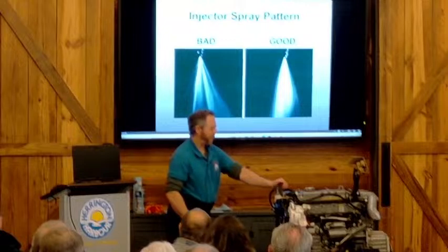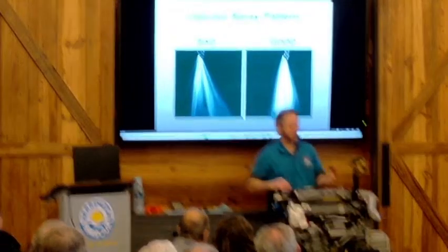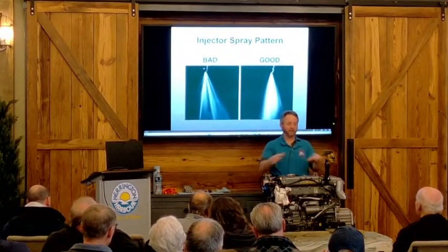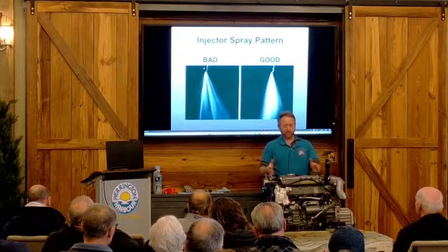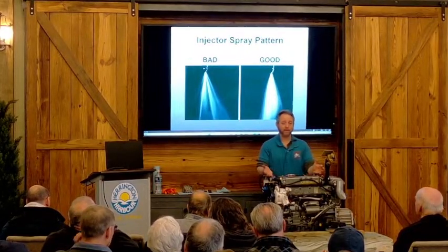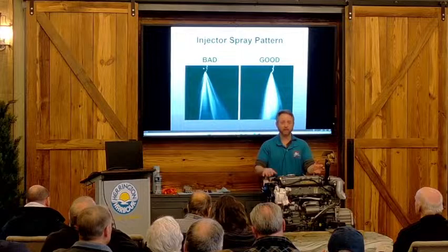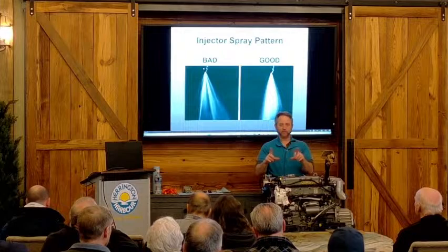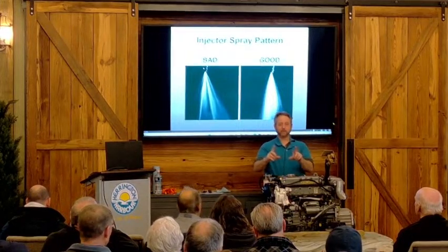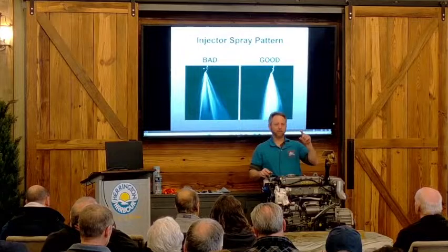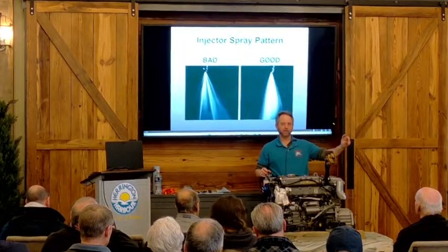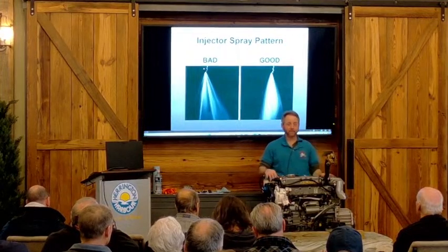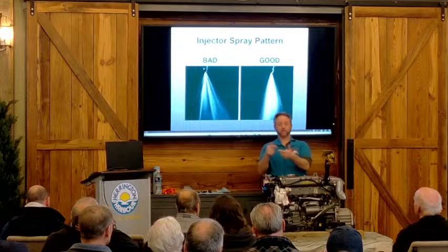Okay, so not running your blowers if it's required. Not all compartments are sealed so tight that the engine compartment's really hot. You can see how hot your compartment gets by going to your hardware store and buying one of those indoor-outdoor displays for weather. It's got a wireless display, and a remote sensor that you can install at the top of your engine compartment. Close your compartment up, go for a boat ride, run it for half an hour at cruise RPM and see what the temperature of the compartment is.